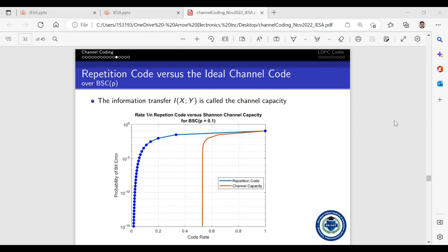Okay, just a few more questions. Will repetition code increase the redundancy? Yes, that R is actually telling us that. When R is equal to 1/3, it means that 2 out of 3 bits are redundant, and therefore the rate of communication becomes 1 out of 3.